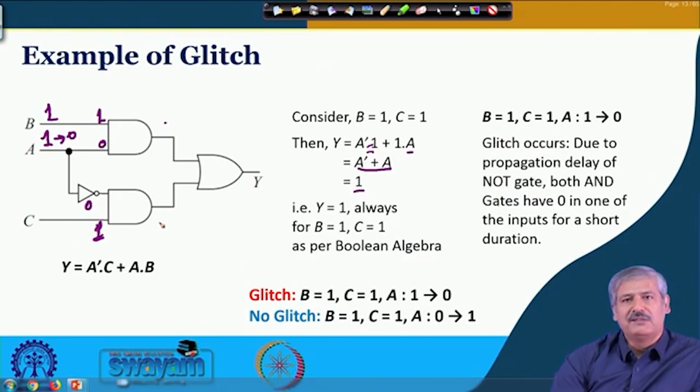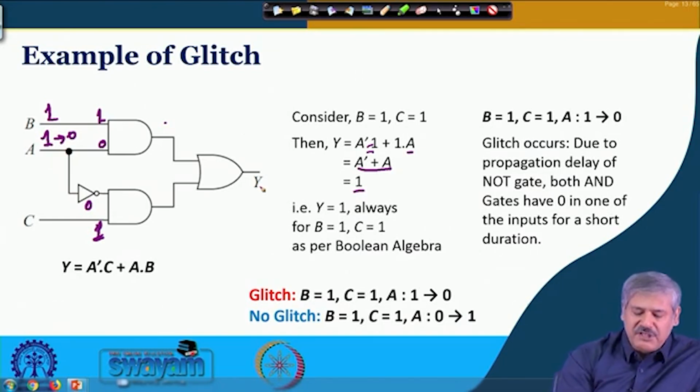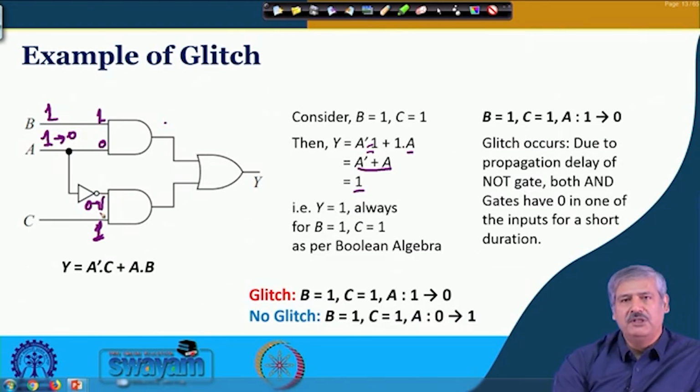So, what we see is that OR gate both the outputs are 0 even for a small duration, after that it will become 1. So, for that small duration, after again its own propagation delay, the OR gate will generate a 0 which was otherwise 1. Okay. So, after that propagation delay, of course, it becomes 1, and then there is no issue. One of the OR gate inputs is 1 except for that transition period.